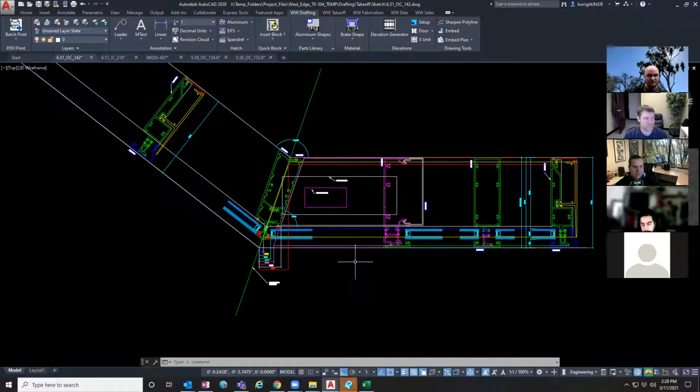Just one side note, back when I used to do these layouts, I did mine color coded as well. But if I had a job with multiple corners, I would create a block that was a center line, let's say white, and then I would just have my series of offset lines, and that whole thing was a block. Then I could rotate that to whatever degree I want. I didn't use polylines for all of my horizontals, but that way, all of my offsets were already done every single time. I could just rotate to the proper angle, explode it, and then just start trimming lines together.